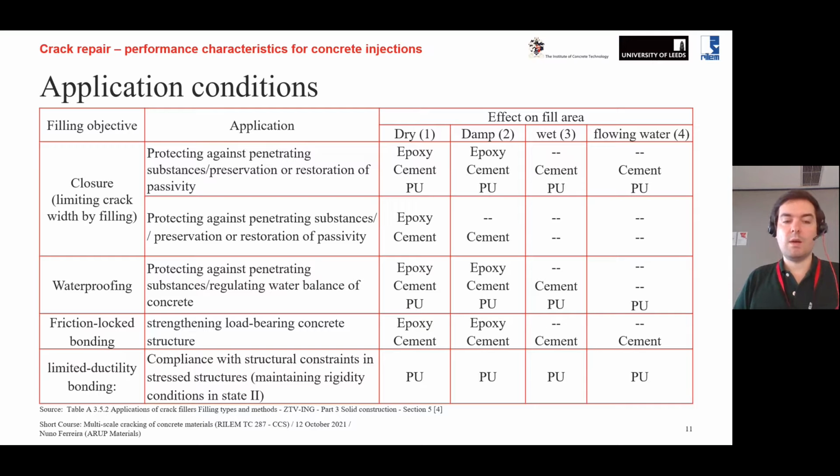This is almost like a wrap up of the presentation in a way. So closure: we basically want to limit the crack width by filling. The other objective could be waterproofing. We may also wish to ensure bonding, or we may also want to ensure some limited ductility.